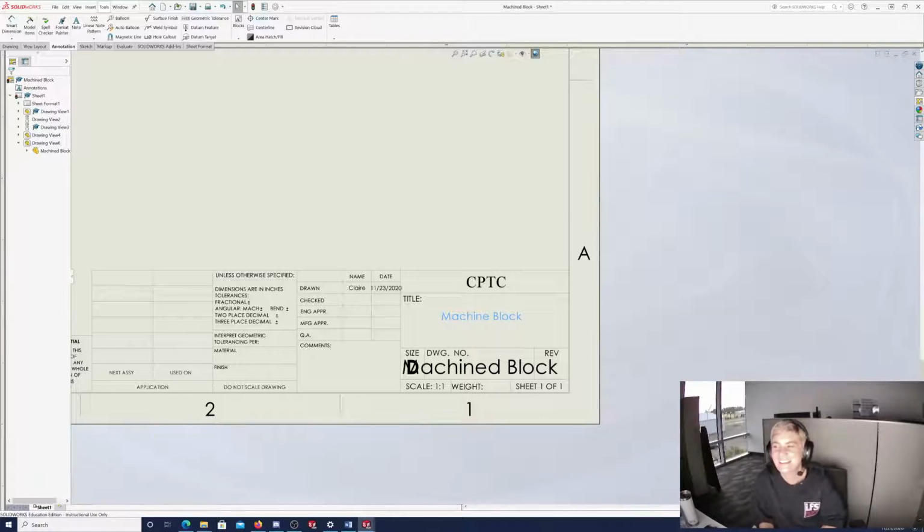Cool. Yeah, I'd say whatever, as long as you have several configurations. I just want to make sure that you all know how to do configurations, because that can be pretty important in a work setting if you're doing drafting or whatever. You don't always want to permanently edit your whole part, but you want to have saved edits of the part, and it's a much cleaner way to do it than saving multiple files on your computer and not knowing which is which. Once you have all your configurations in one part file, it just makes your life a million times easier.